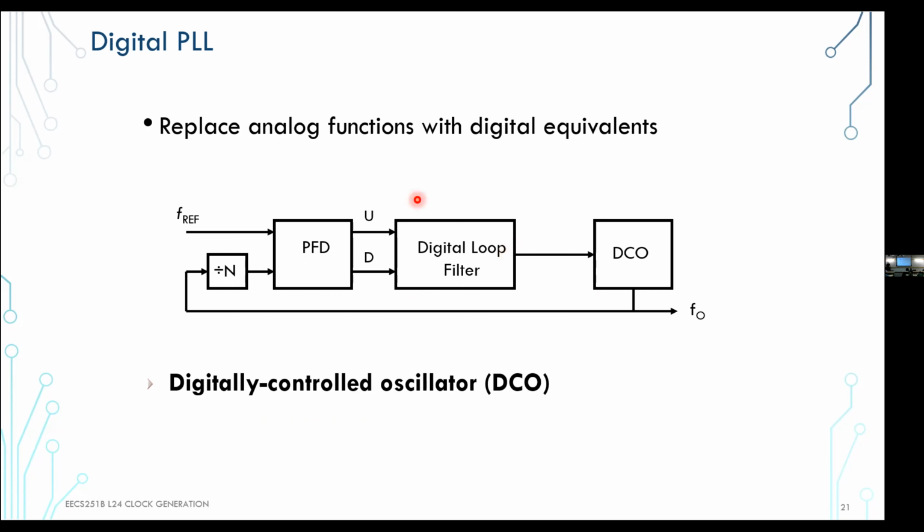The nice thing about the digital loop filter, it offers you the flexibility to set more flexibly the bandwidth of the loop, because for the other case, you need to physically change the CP. So you have to have it segmented, and there's a whole bunch of problems with all these things. So here you just change some coefficients in the accumulator and you're done. Or in the proportional path.